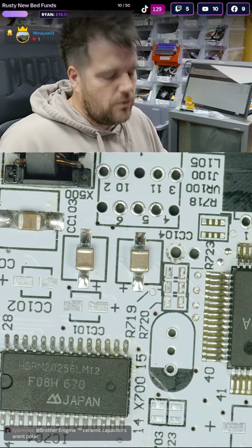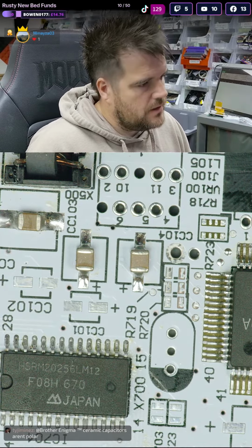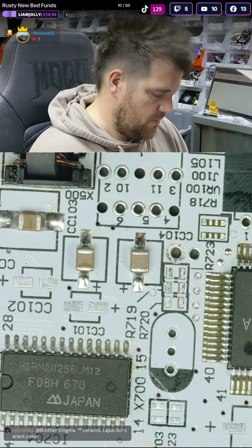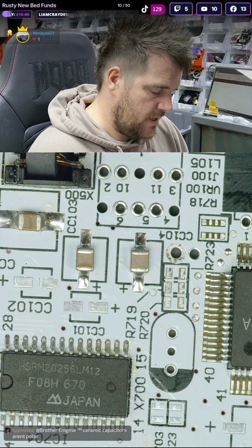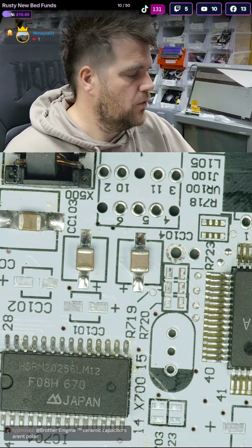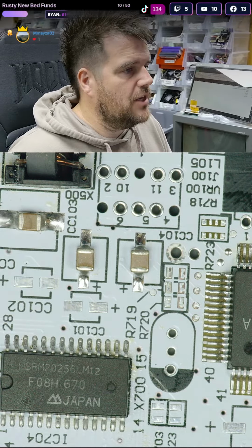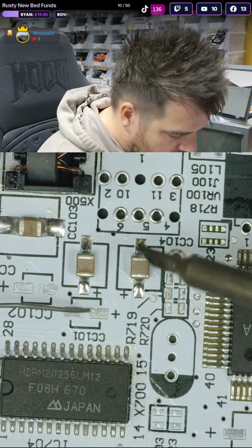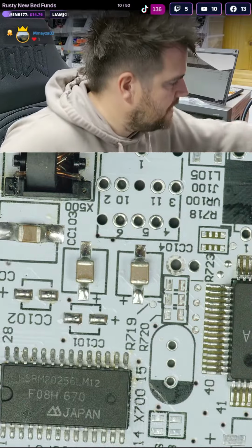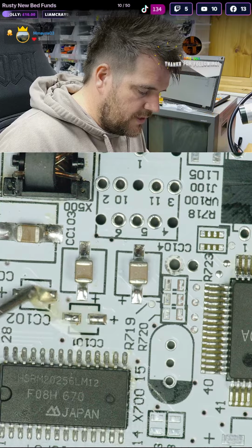Right, CC101 and 102 are 33 microfarad. So these can be 47 uprated because 33 in aluminiums, it's not going to be anything specific on the filtering. This is going to be more of a stability cap, a bulk cap if you will, and ceramics tend to be a little bit down rated on the capacity versus aluminiums. So when you're redoing the circuit with ceramics, sometimes depending on where they're used, you want to slightly uprate them, and 33s are not that common anymore.